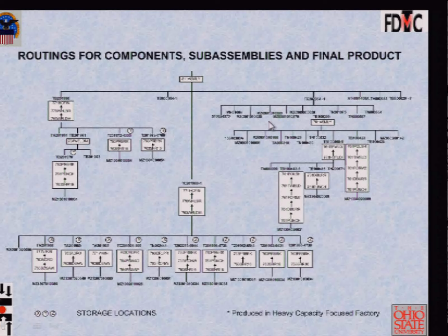Okay? So, where would you put your supermarkets? Naturally in front of the welding stations. So the MIG welders here, there's a MIG welder here, there's a sub-assembly here, there's assembly here, there's assembly here. So really, you would put a supermarket in front of the MIG welder, you would put a supermarket at this assembly. You know, it's logical.